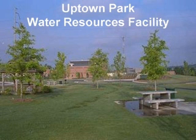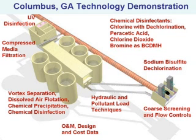In the initial stages, they looked at what flow rate they need to treat, and they concluded that the 90% rainfall intensity was the knee of the curve design criteria, that we would basically treat 90% of all the rainfall hours, the runoff from all the rainfall hours. And those excess flows would go pretty much untreated into the river system.